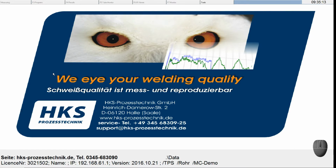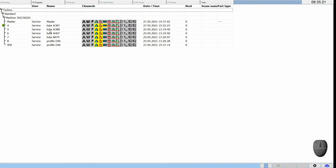To open the checking programs in the WeldQAS software, you can use the button or the function key F3. This can also be done during monitoring. The main menu of the checking program setup can be seen now. In the middle you can see all the checking programs that have been taught in so far. These are numbered clearly from 1 to 999.